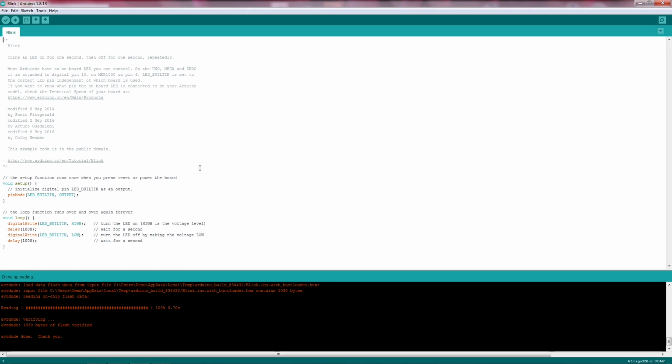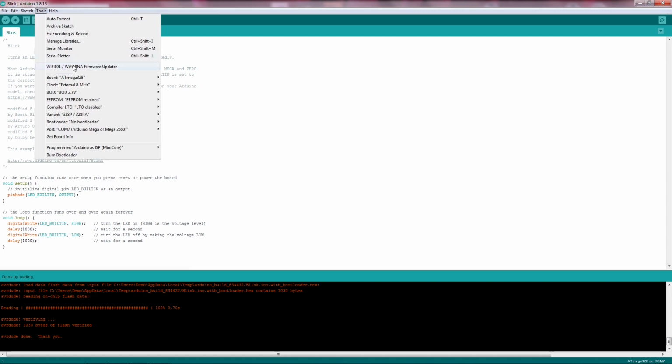So when you go here, choose tools and choose an external 8 MHz, and then this gets put into fuses via burn bootloader, you're not actually saying it's going to be an 8 MHz crystal. In this specific case, for example, there is a range of crystals from 8 MHz and above, and that's what's there in the fuse configuration.